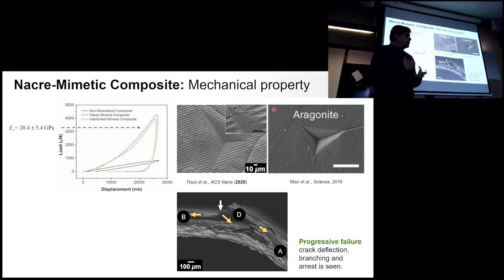So the measure of fracture resistance is basically if a material gives you an indication of cracks, we can call that material tough, because it gives you some signs of cracking, some minor microcracks or such, so that you can replace the material, or you can do some repair work, to still make use of that material.